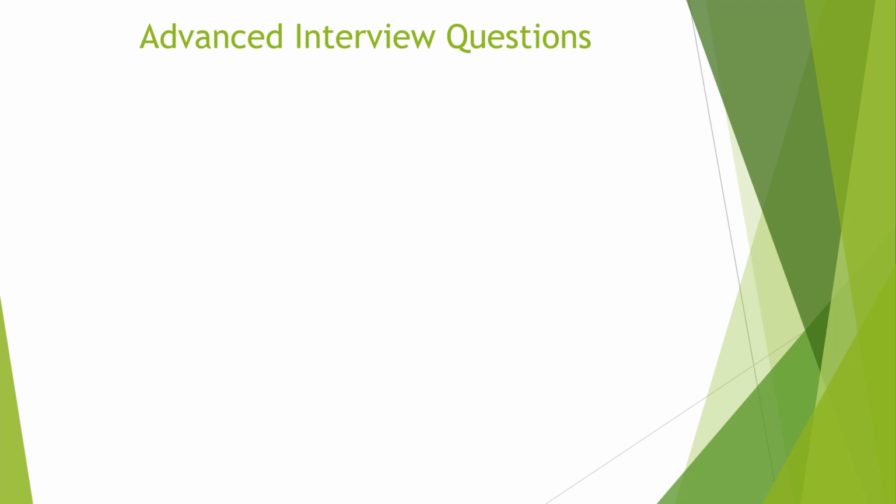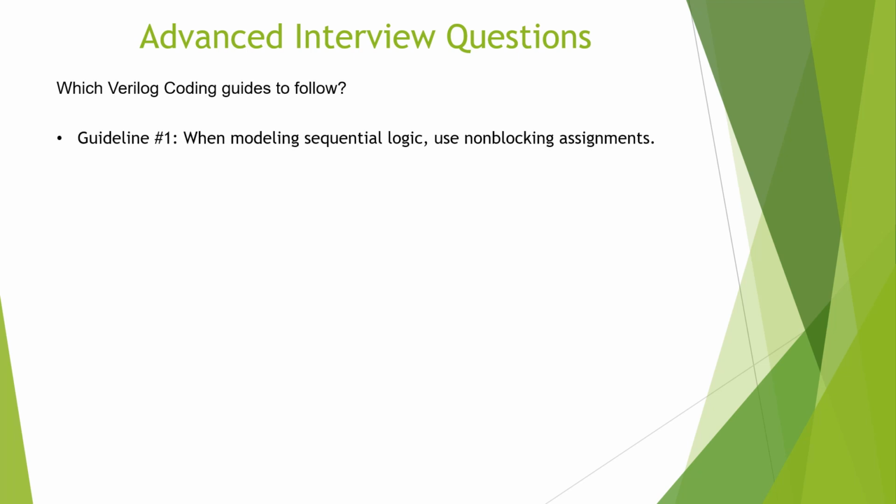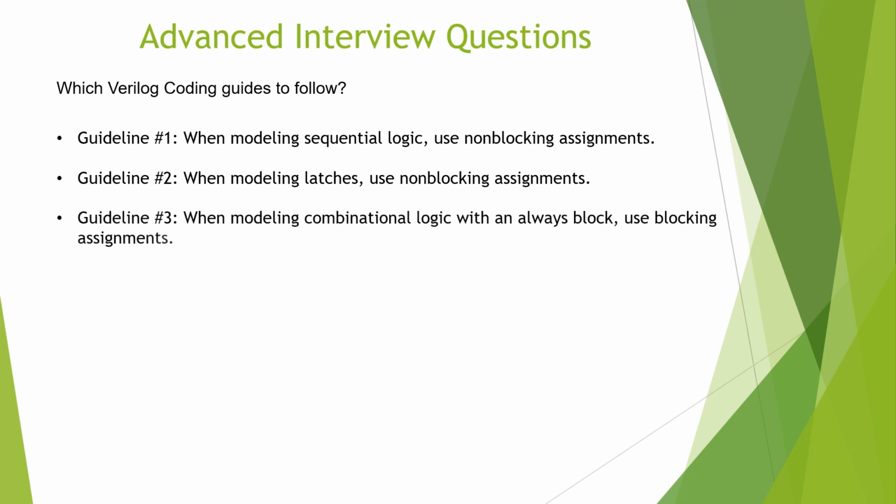These guidelines are also a result of countless design, debugging, testing, evaluation, and experiences, and also feedback from billions of functioning products. So the first guideline is when modeling sequential logic, use non-blocking assignments. The sequential logic is flip-flop based logic. So when you are writing the design for a flip-flop, use non-blocking assignments. The number 2 is when modeling latches, use non-blocking assignments. Latches are also memory elements like flip-flops, so use non-blocking assignments when writing the code for latches.